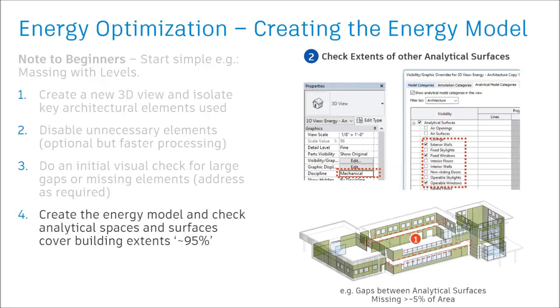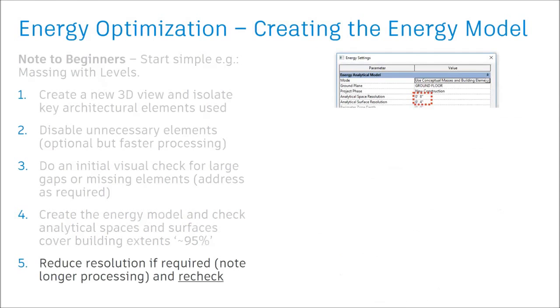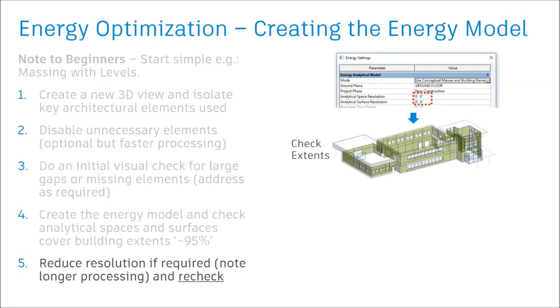And so this is where the resolution setting comes in. If you change the resolution, and I would always suggest doing it incrementally, when you get to this 8-inch, 4-inch point, I find that's the sweet spot. It's kind of fuzzy logic, so it could be 9 and 5. You get very, very similar results. I generally keep them at a 2-to-1 ratio. And what you'll see then is that you'll get a much tighter model. It won't be perfectly tight, but it'll definitely be above 95%, or in other words, within a couple of percent of the physical measures.